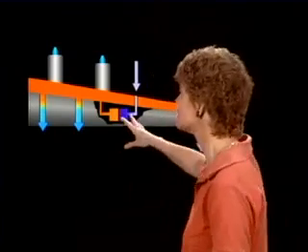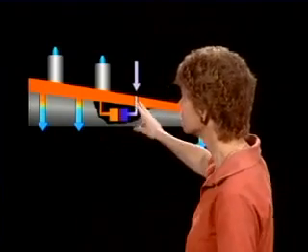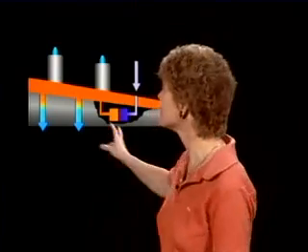Now, if you've cleaned or replaced the filter element in the fuel system on a combustion heater, you need to be very sure to pressurize the system and check all of the connections for leaks. Because if a combustion heater starts leaking fuel, you've got a real fire hazard there. So you want to pressurize the system and make sure that you don't have any leaks at the connections if you've broken the system, if you've cleaned or replaced the filtering element.